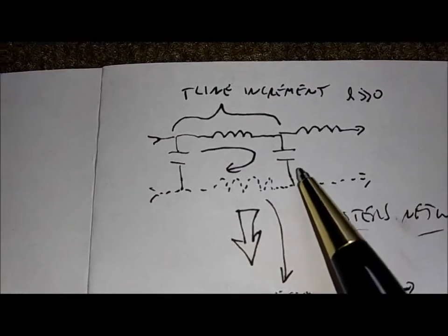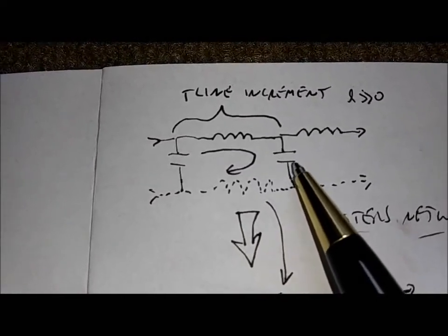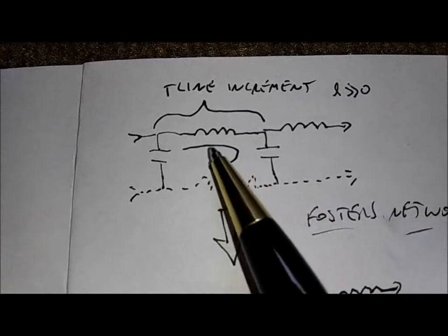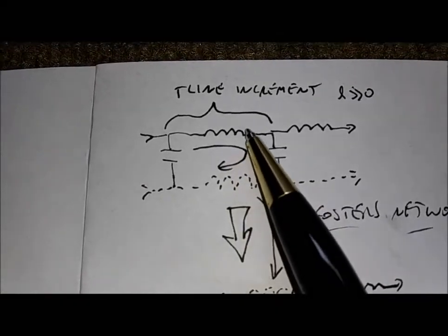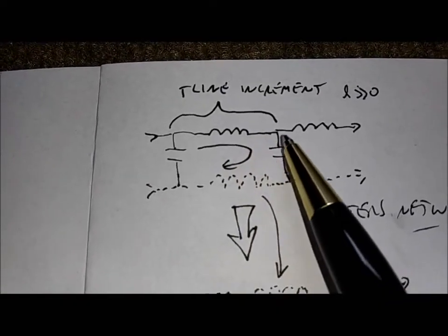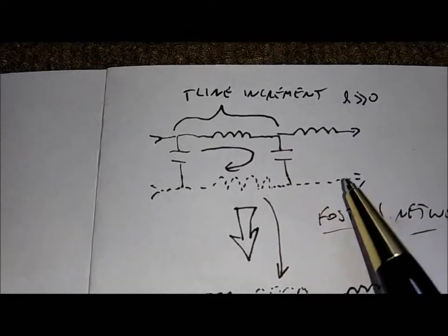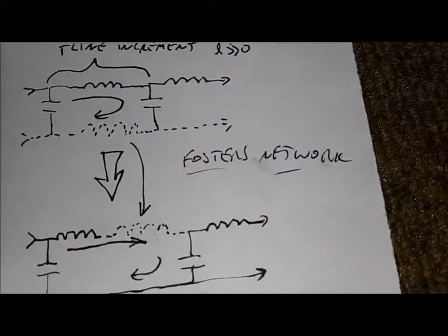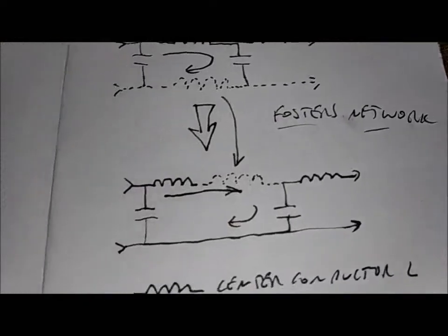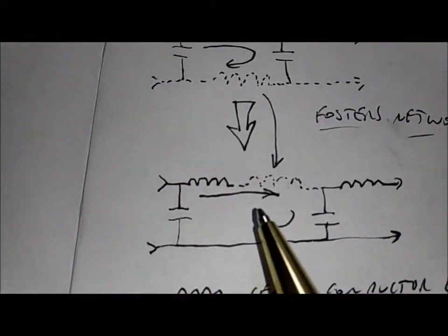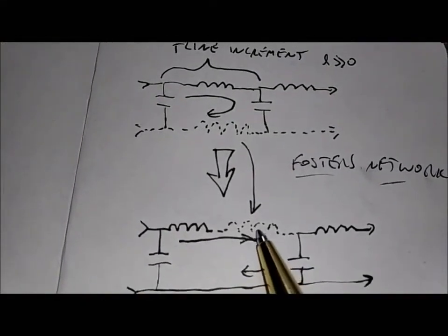Hams do it. They have no idea why they do it, and it screws up the transmission line. So basically this repeating LC section is what a transmission line is. And it's in theory a Foster's network. Down here shows the shield inductance in series.